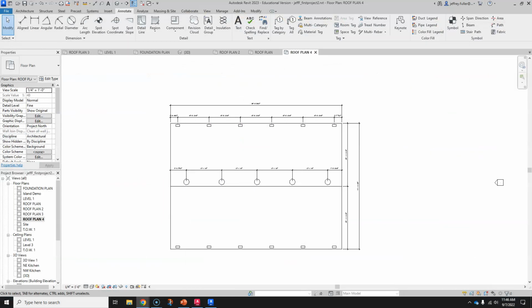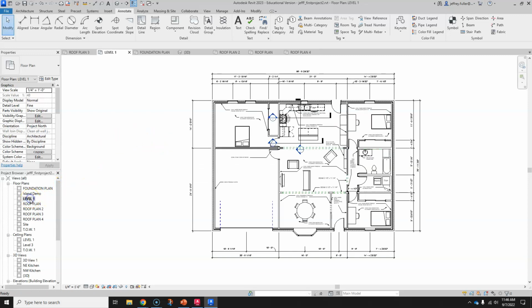Now, where do we locate those? Well, we come over here to our drawing, and we might have to take a look at our level 1 again to see where those items are. Like our sink for the kitchen is about right here in the middle. So I'm going to put a mark for a plumbing vent here. I'm also going to put a water heater eventually in this garage. I have not put one yet, but I'm going to. Or no, actually I have a washer and dryer over here. But anyway, I'll put a vent right here.